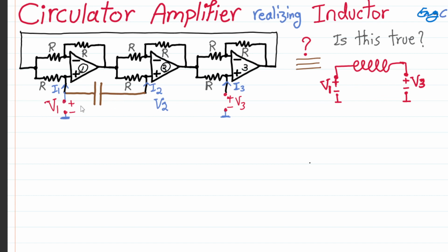it is converting a capacitor into an inductor, and it has a lot of practical application because if this is true, it means we will be able to realize potentially high value inductors with high quality, or high Q, that practically would be either super difficult or impossible in some cases if we were supposed to have an actual passive inductor in the circuit. So there are a lot of potential applications for this as long as we can keep the circuit stable. Okay, so let's see.